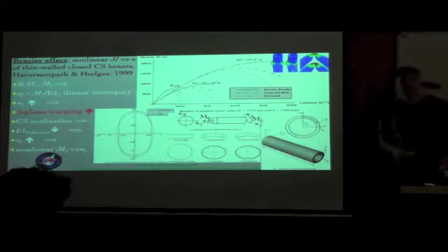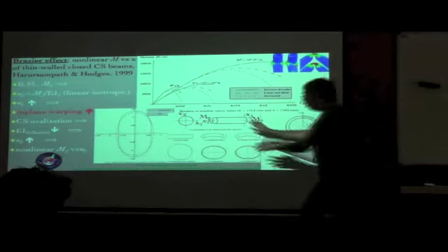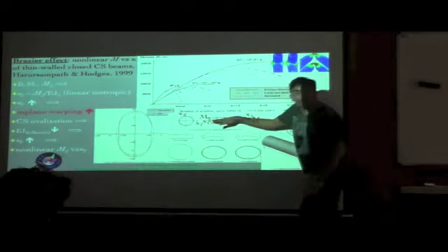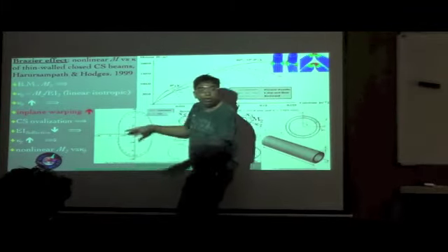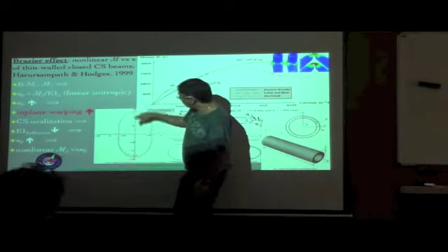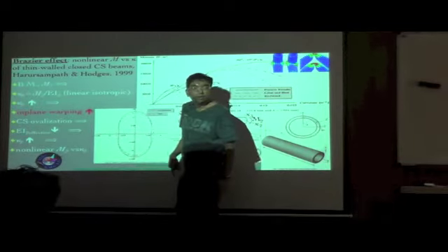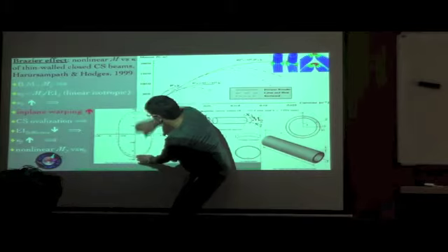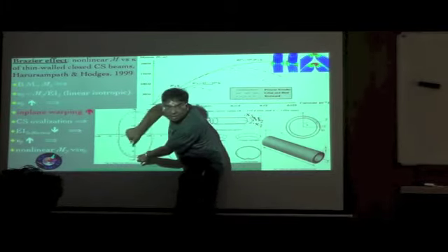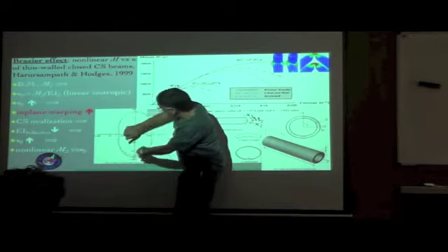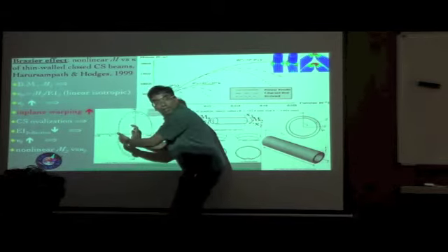So which one is the 2-axis or AE2? In all these pictures, the horizontal axis is 2 and the vertical axis is 3. But in this picture alone, this is x2 and this is basically x3. Okay, I'm sorry, so this is x2, the vertical is x2, and this is x3, because the bending moment is basically applied like this about the x3 direction, because of which the flattening basically takes place.